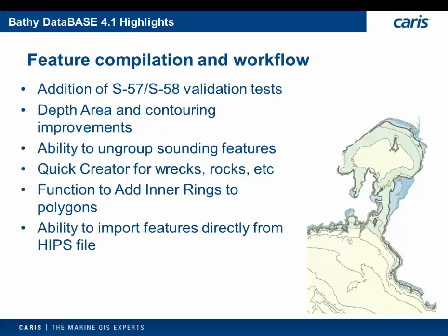We moved the tests related to feature geometry and some of the attribution tests into the validation window in Base Editor. And that's going to let you make sure that you're sending out contours with valid geometry and that sort of thing off to your chart production system. And remember, with those validation tests, you can always create your own set of custom tests.